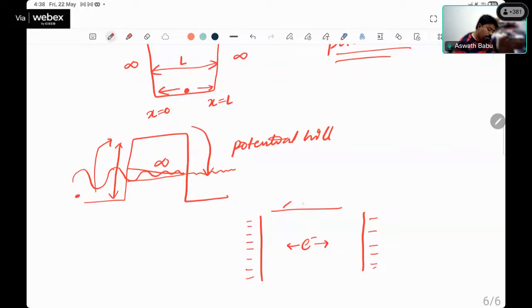I'll have one more negative plate on the top. You know what happens in this case? The electron is repelled on top and bottom. So in all the 360 directions, I create repulsion on the electron. In this way, I'll confine the electron to a very small region. Not only one electron, I can create many such electrons confined to the small region. This is how we can create a quantum dot having a certain number of electrons confined to a small region.